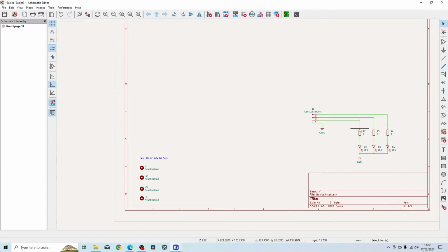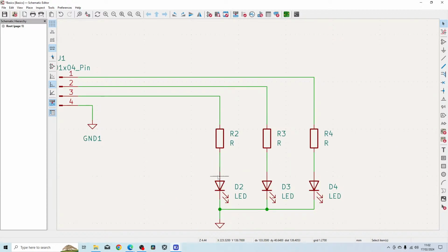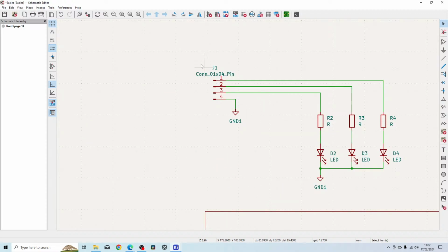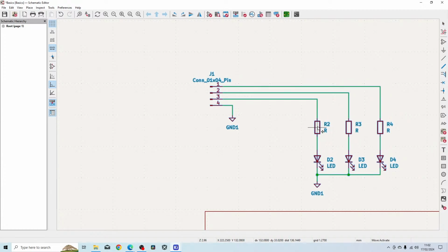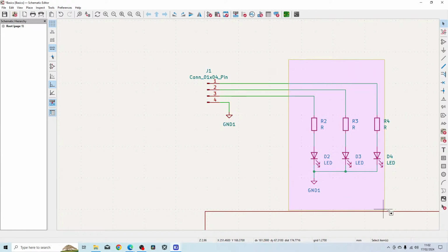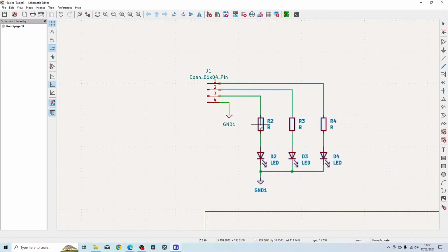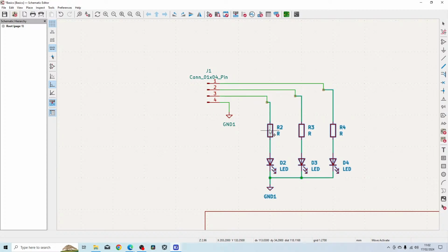So let's say you want a clearance of, I don't know, just random 2 mil from this component, you should state that somewhere. You should give a rule to the PCB designer so that they follow what you need. Most of the time it's likely that you're designing the boards, and then you still might want to do that because it helps you avoid mistakes, which is the main thing.